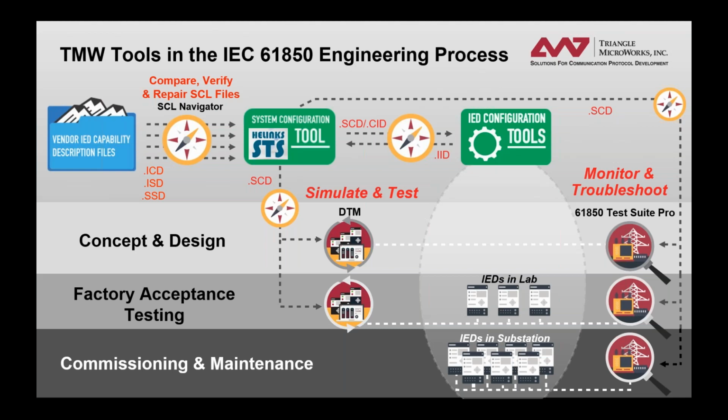Okay, how buffered and unbuffered information really works in IEC 61850 is completely based on the FIFO concept. How does this really work when a controller is working as a client and a relay is working as a server, where information goes to the SCADA through the 104 communication protocol?